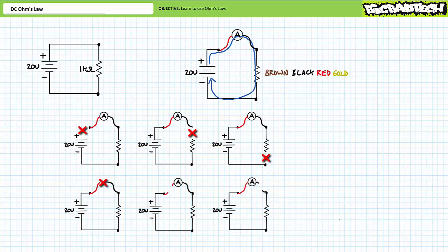Additionally, consider the consequence of damaged test leads, or test leads that are not properly inserted, that prevent completion of the circuit. In summary, if you observe no current flow, you are definitely dealing with an open. Having determined an open as the source of your problems, it's now up to you to find it.